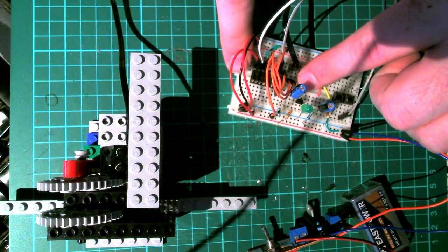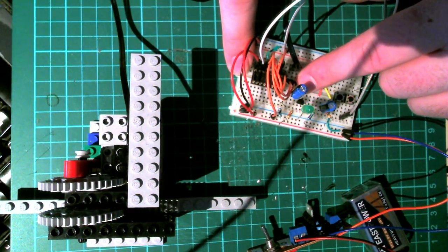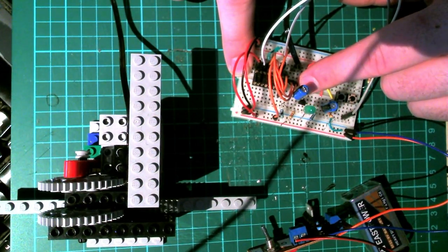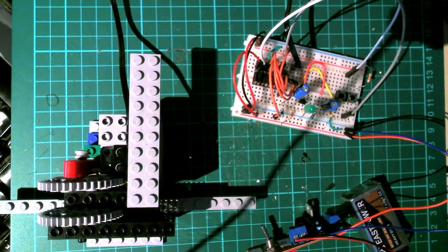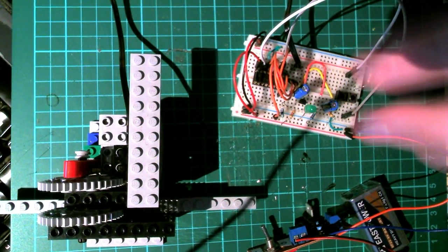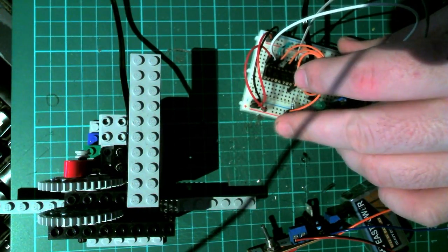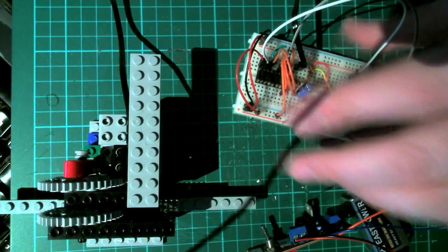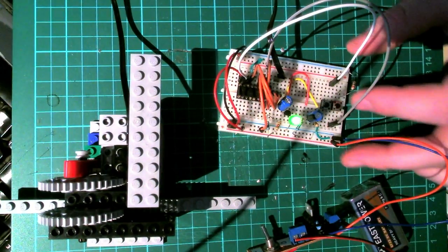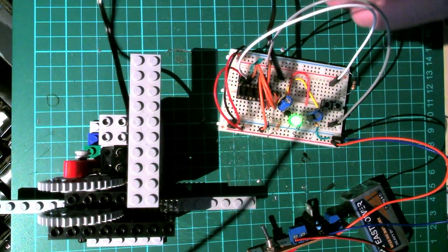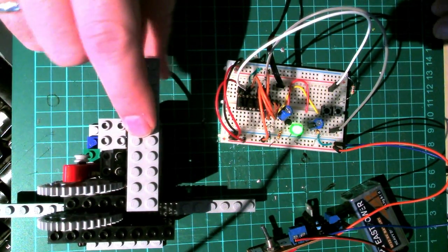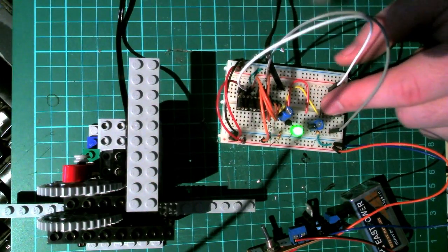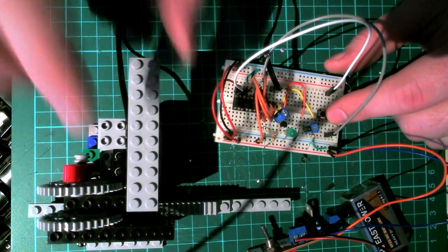This part right here is the H-bridge, and it's actually called the L293D, the chip, and it's a standard H-bridge. And if you notice, we're only using one side of it, so it has a potential we're not using. There we go, and it's hooked up using this wire directly over to the Lego motor. So when I press these buttons, oops, that's too far.